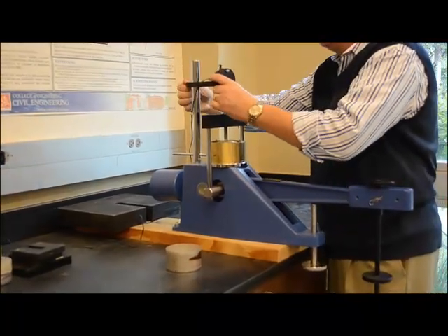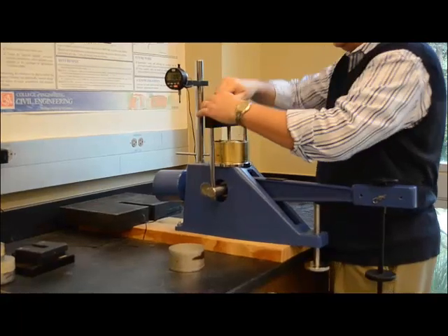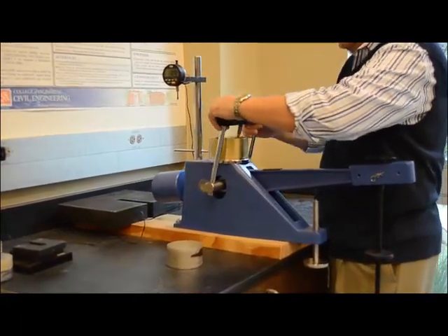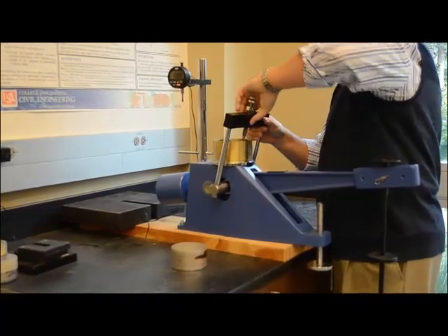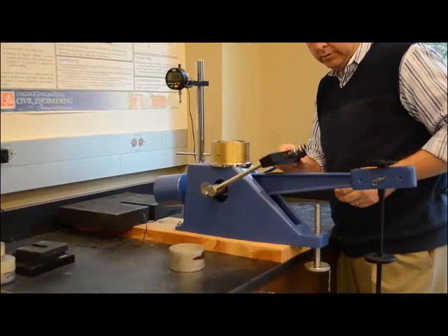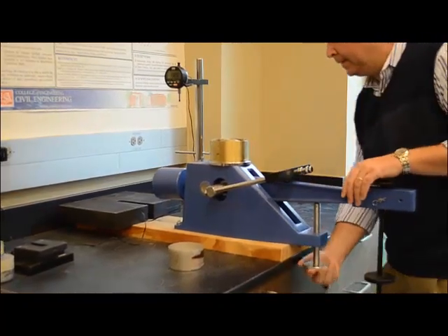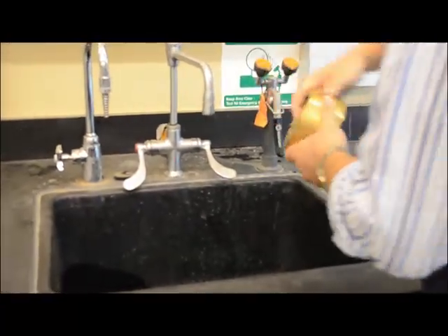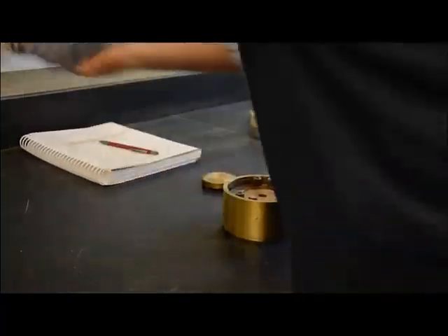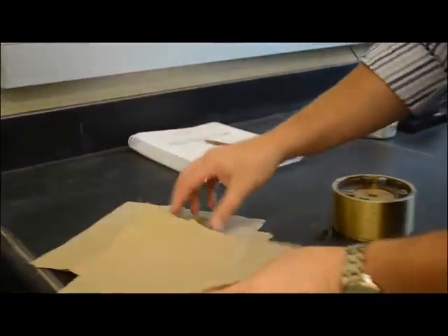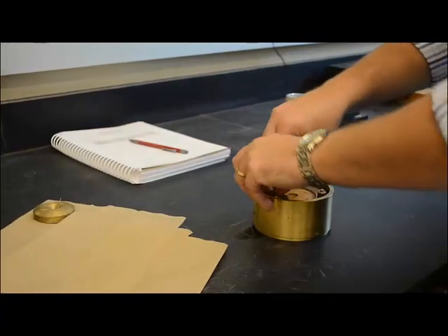Now, what I'm doing here is this is the final one. So I've completed all of the increments of loading. So I'm taking the soil sample now out of the water bath. Okay, but I want to be clear that you need to make sure that you do all of the loading increments the same way, where you lift up the loading jack to just touch it, to reset the digital gauge, and then start the time over again with the new load that's being placed. And you do this for every increment that's necessary.